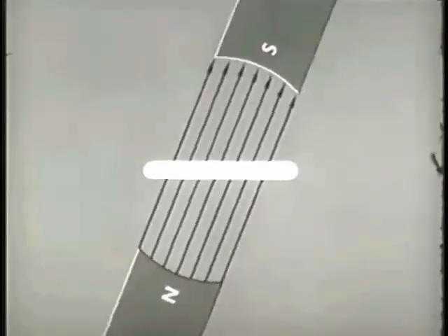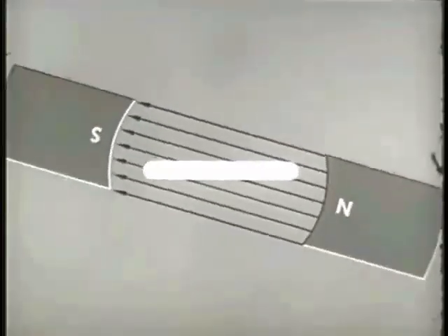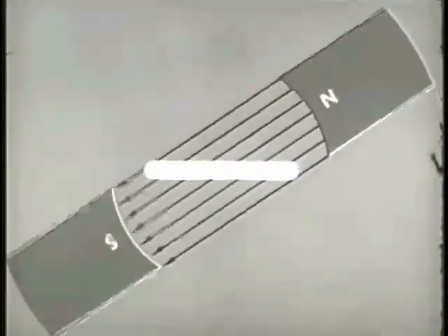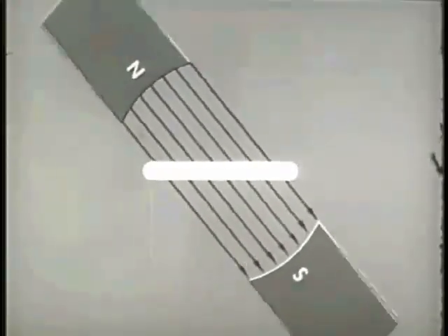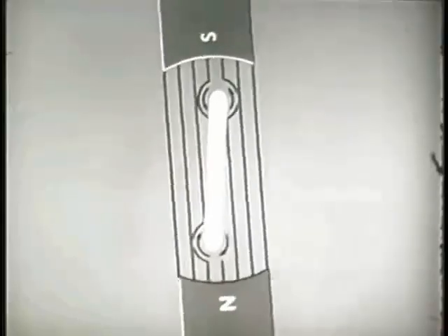This, however, is an impossible situation. For if the rotor stops while the field continues to turn, relative motion will have been re-established. Lines of force are being cut once more. An EMF is generated, and the resultant magnetic field will cause the rotor to move again.